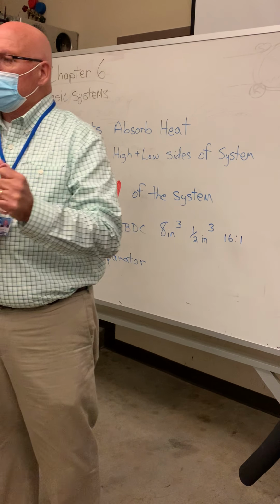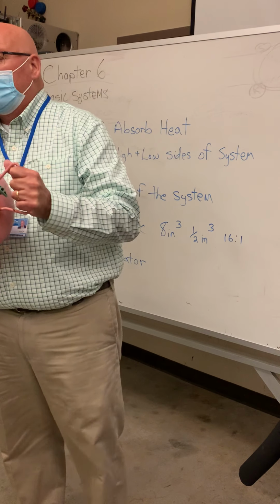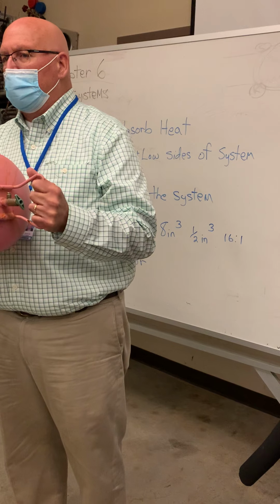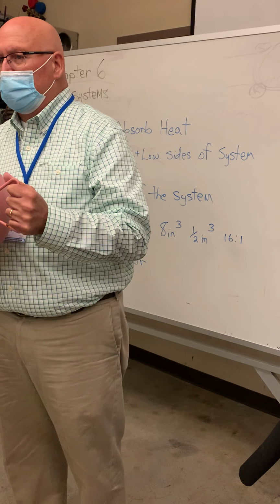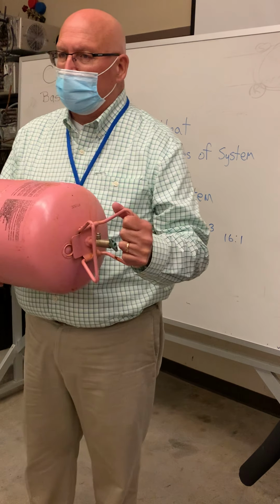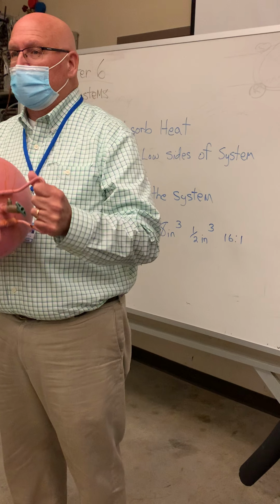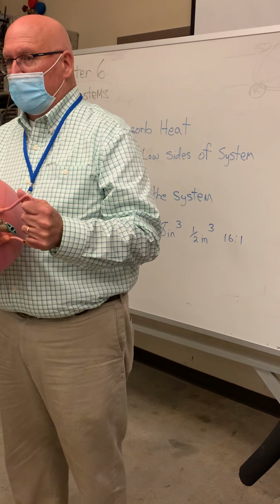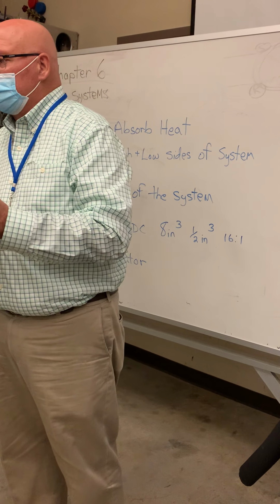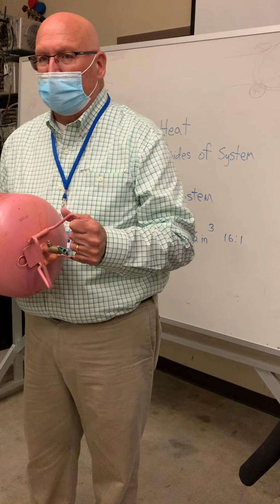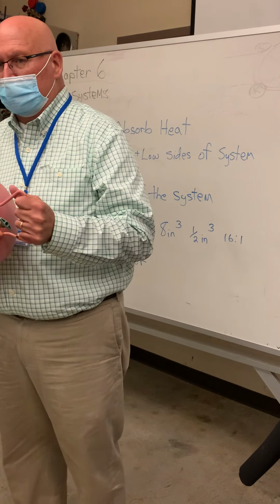Right. So here's what Anthony's getting at. If it's 70 degrees in this room, and we have the rule that hot goes to where it's colder, I need to lower the temperature of this refrigerant vapor to be less than 70 degrees. And the more I can lower this refrigerant vapor, the faster I can absorb heat.